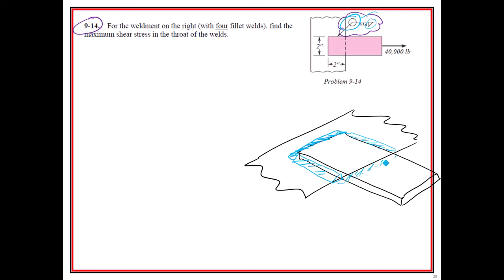And this is actually pretty good practice, especially on ships, because on the other one, there's actually ways that moisture can get inside in between here and cause corrosion where you can't access it, you can't chip it and paint it and coat it and do anything about the corrosion that's on the inside. But here, we've pretty much sealed the thing off. So we're preventing that. So most of the time on a ship, we'd actually want to do this all the way around.